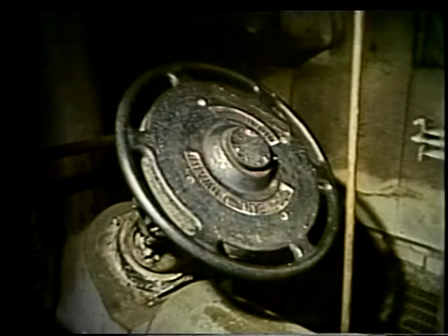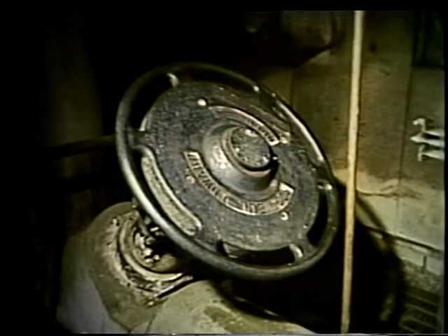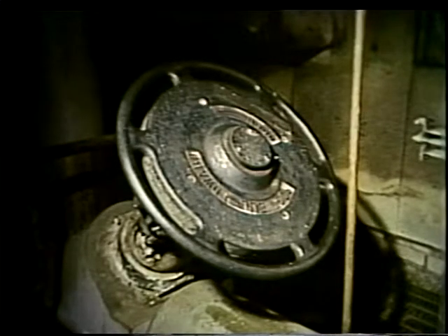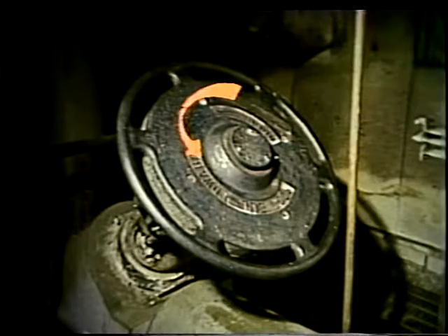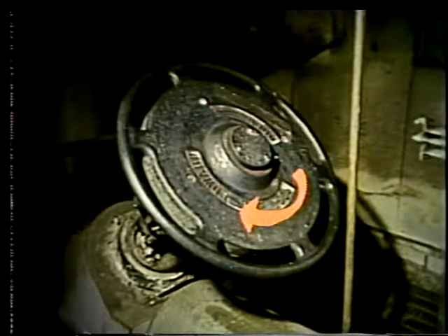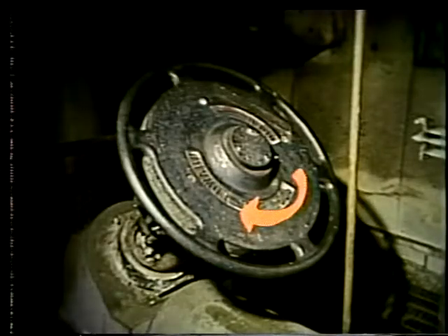This valve has a modified hand wheel called a knocker. It's a type of hand wheel that is usually found on very large hand-operated valves, which are designed for heavy-duty service. The hand wheel on the knocker valve is weighted and has approximately a 1/4 turn play. The valve is opened or closed in this way. First, the hand wheel is turned in the opposite direction of the desired rotation. Then it is turned as hard as possible in the desired direction, slamming the stem into motion to raise or lower the disc.